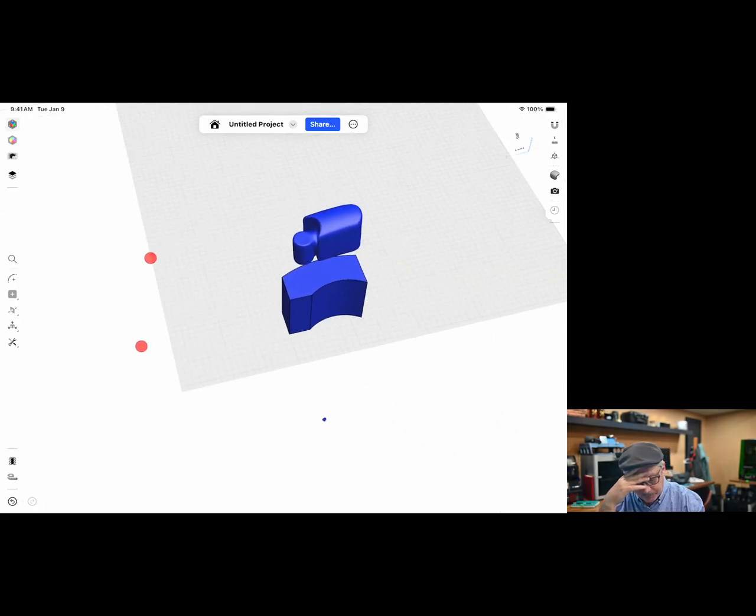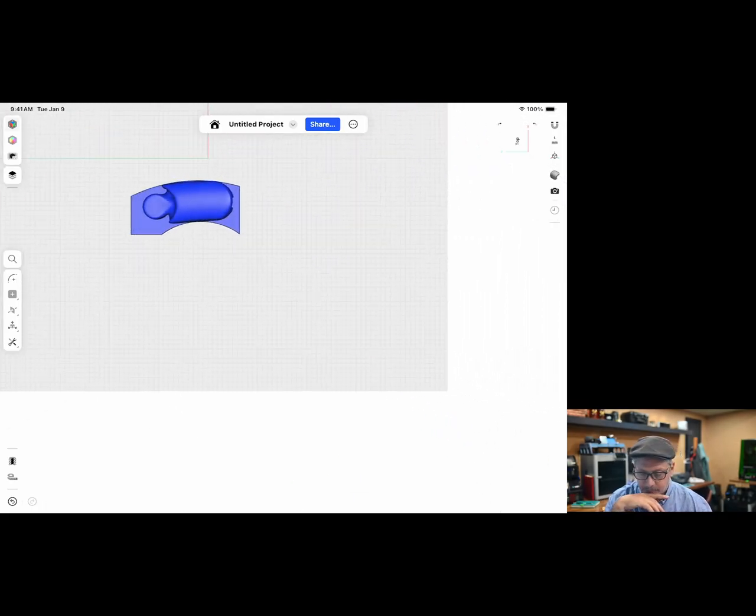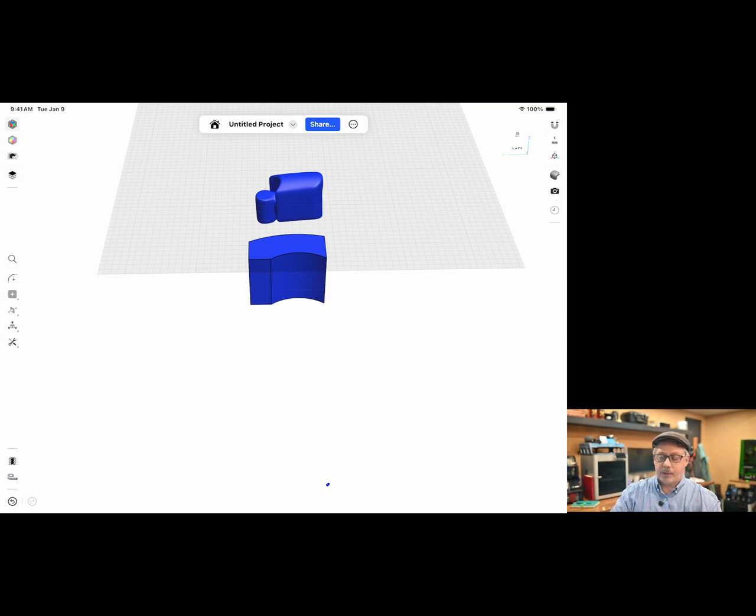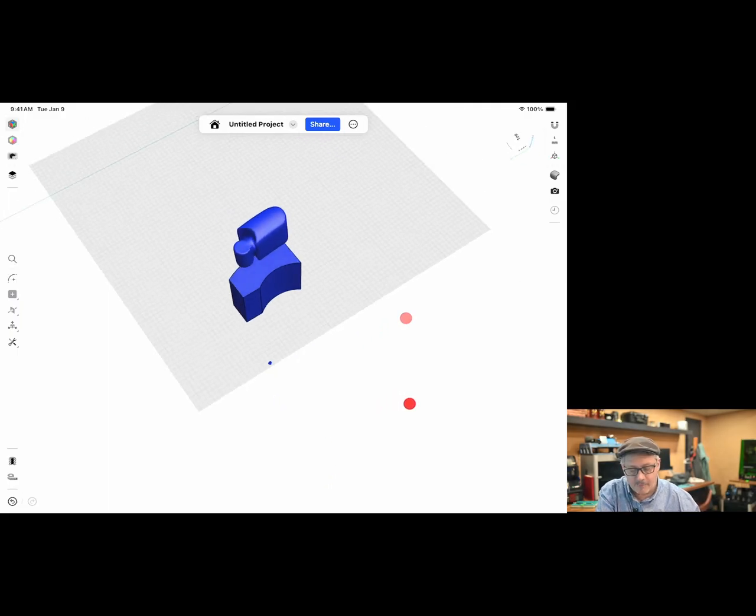And now you can see that we're starting to get there. And there's lots of different ways to do this, but if you want to figure out what the radius is and then throw it down, this is a way to do it. Especially if you've measured the device and you've got the exact measurements. But if you don't and you just have a mesh file and you just have to freehand it anyway, then work on the plane above it, drawing out your sketch, and then extrude that sketch down through the underneath object to shave off the pieces you want. And when you're done, you'll end up with a very nice vector.